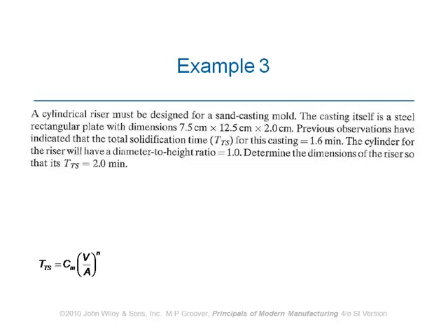Are we making any progress with the problem? Yeah? Why are we interested in solidification time TTS for riser which is greater than that of cavity? Because it should always be the case. Always the solidification time for the riser should be greater than that of the cavity. And what type of geometrical shape makes this possible? Well, which shape makes it possible or more desirable to increase the solidification time as much as possible?